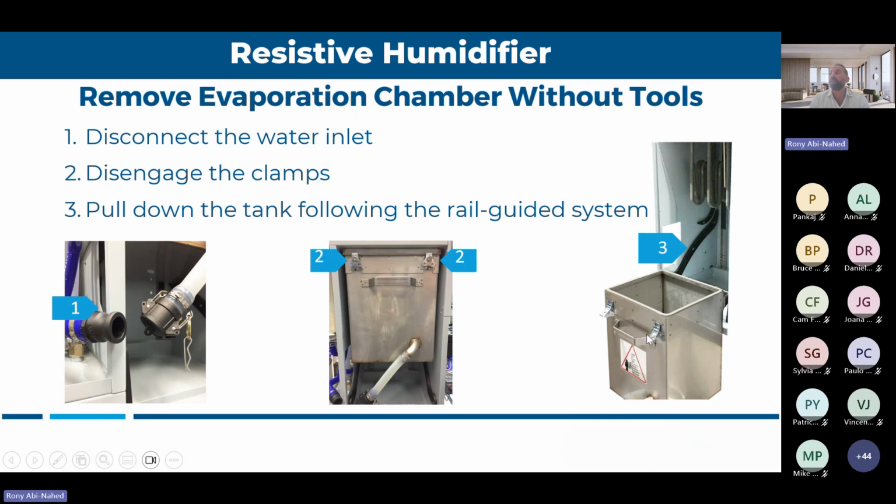During this period, you lost your set point, so you're not plus or minus 1% all the time. Now, if you go with our RO system, you don't need to go through drain cycles every 4 to 6 hours because we know it's pure water. So we tell the unit, don't drain, just keep running the whole time. And that's how you can achieve your precision out of it.